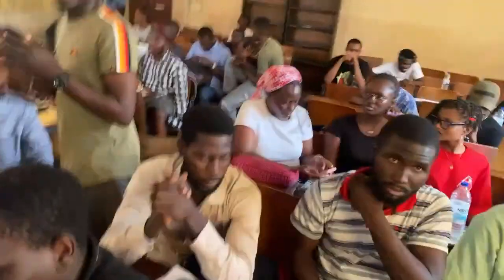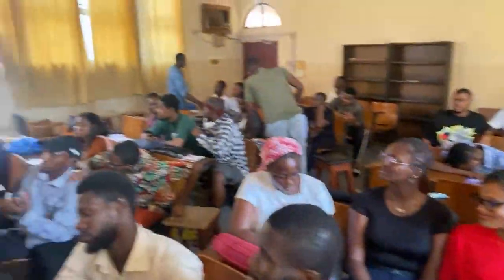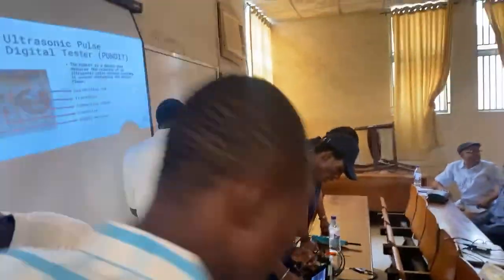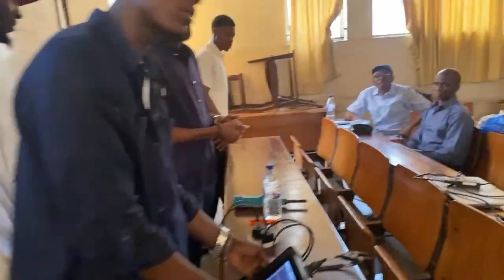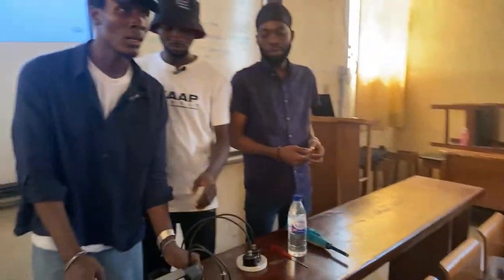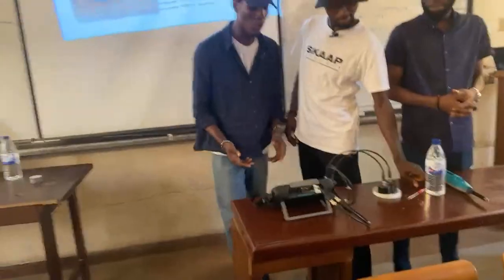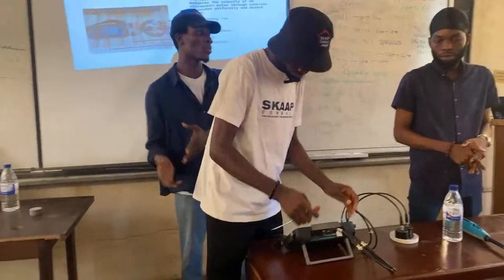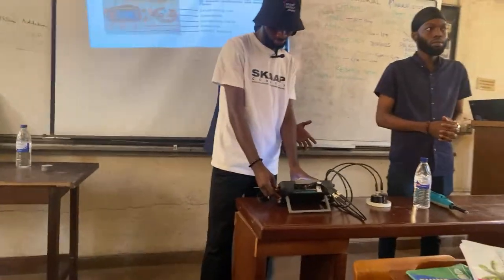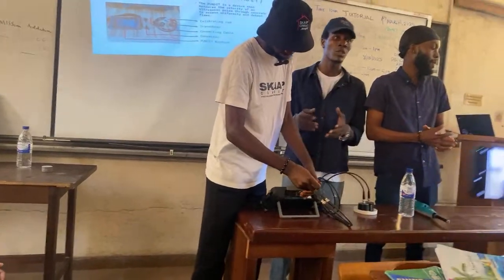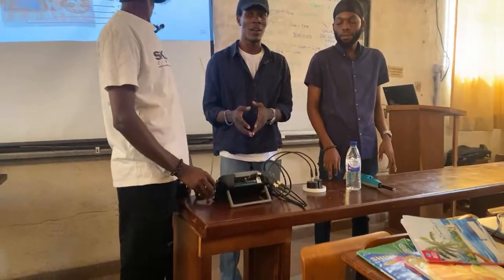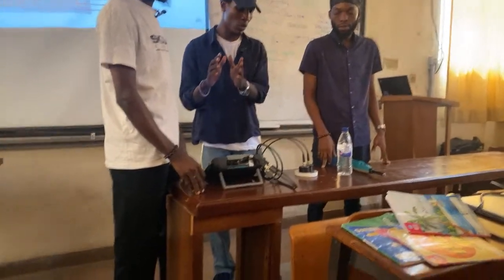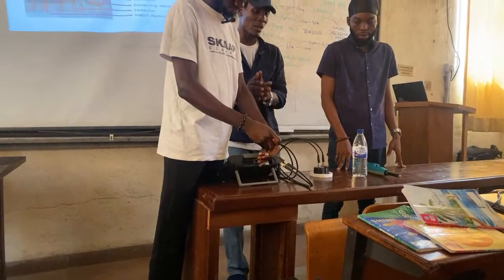All right. So from here, once we are done on any site, we have what we call a transfer cable, where we download all of this information into the computer. From the computer, we can then run the analysis that we need to ascertain the strength, using the correlation curve that we already have as an independent lab. So that's about it for the UPV, how to carry out the UPV and set it up.